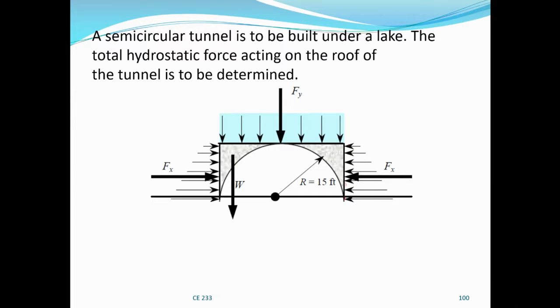So Fy is straightforward. The pressure due to the height of the lake, the pressure due to the water, will be used to calculate Fy here, which is gamma H, the pressure, times the area, the area of the tunnel.